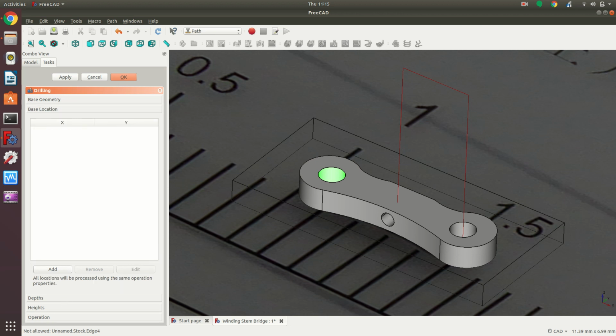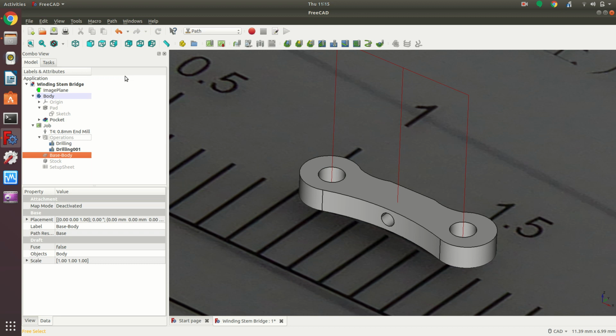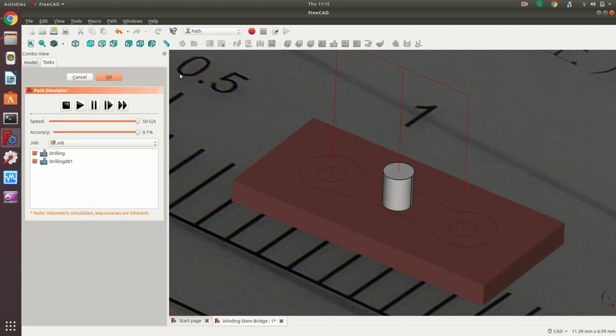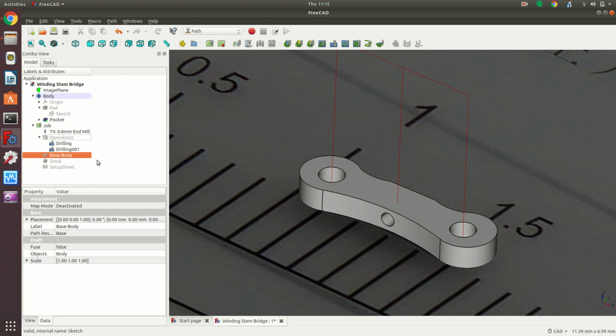What we also want now is the retract height. Let's set it to 0.3, just out of curiosity. See if it does anything. Got that, and we will check what it does. It shows a bit less. But this is definitely a positive measure, meaning it goes up. I don't quite get it. Never mind, we'll ignore it. Worst case, we break the tool.